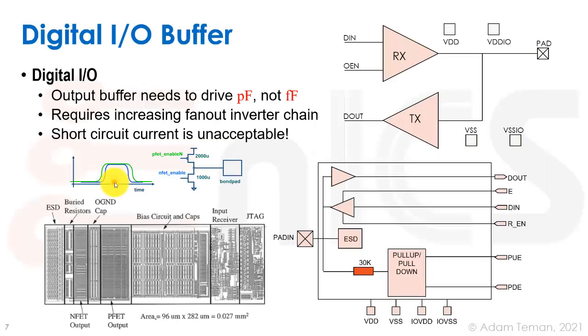So going back to where we saw this, a digital I/O buffer is, as it says here, an I/O buffer. It provides both input and output. So this is kind of an easy schematic of looking at it. What we have is the output buffer over here, which drives the pad, which is the connection to the pad that we saw before. This is the external part of the chip. This is internal to the chip. So we'll have this part that drives out of the chip, and we'll also connect this to the gate of a buffer that drives into the chip.